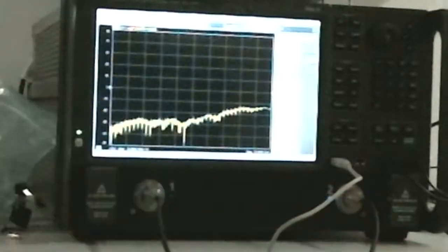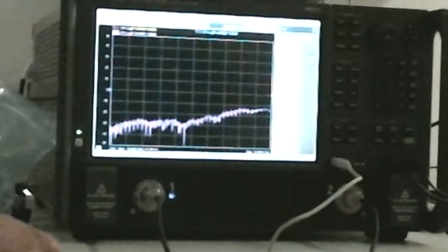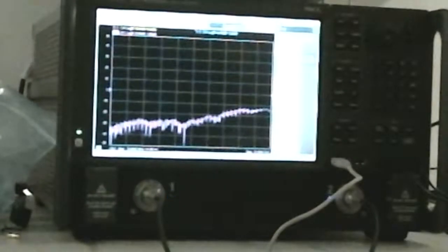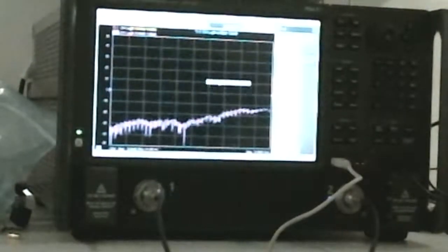And this is actually the response of the cable. This is why I wanted to show you some different things here under trace. Right now I'm measuring S11, and I can add a few other traces. You can also just right-click and add a new trace. You can do it from the front keys or you can use the mouse. If you do new trace here, it asks what you want to measure. Maybe S21? And you can hit OK.